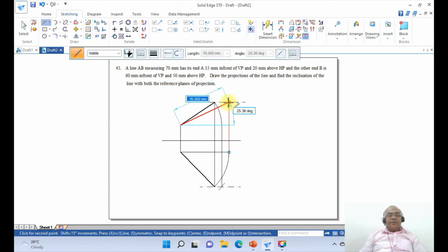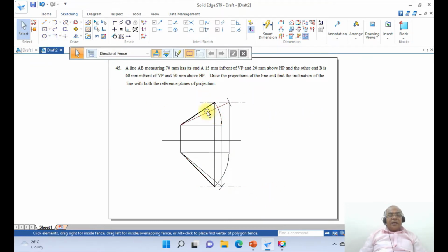You take this between these two, and similarly between this line and this intersection point. Now the true length line should have the thickness 0.25. You select between these two and make it 0.25, but the display will not show it. Once you take the printout, you will get it in the printout. So here the line point will be xy 0.13.